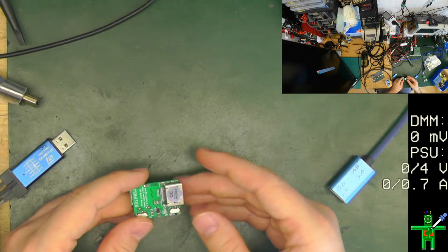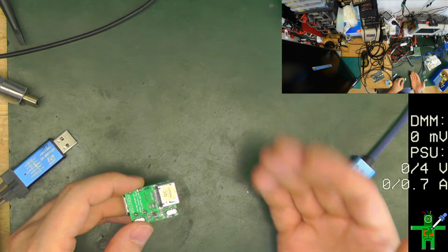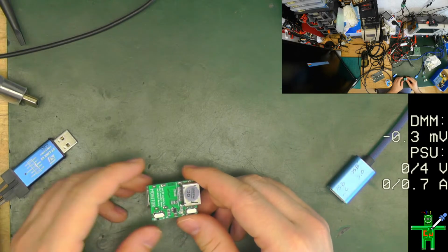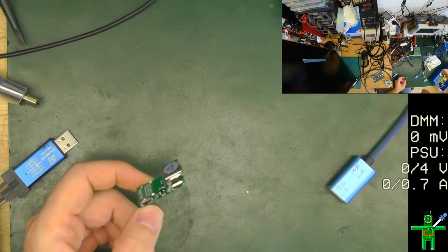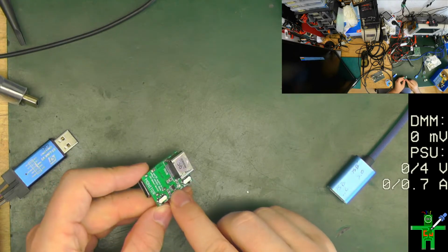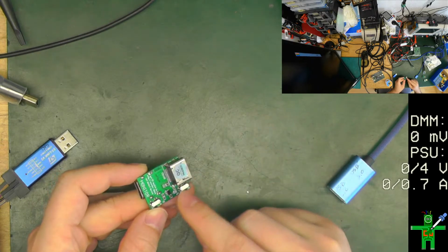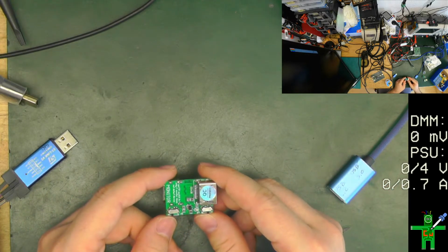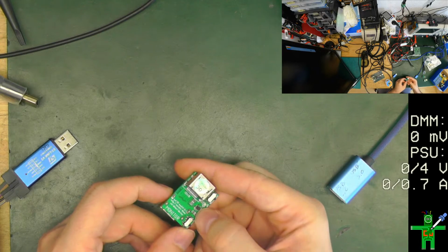You also have that over VGA, DVI, and even DisplayPort. This is very common for everything. And you still have to make this information available, but in a secure fashion. This is why there is additionally an EEPROM where you save this EDID information, which can be read out. It can be more complicated, but very often you can get by with just an EEPROM.